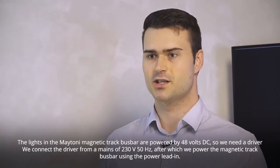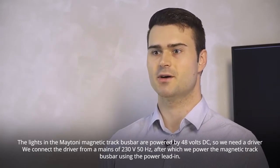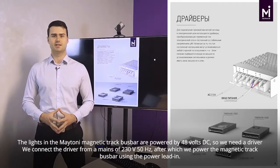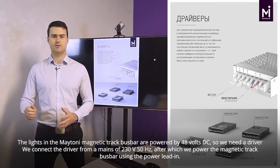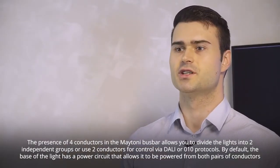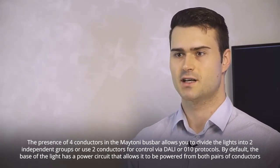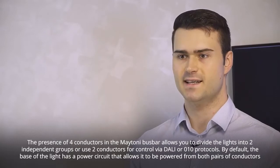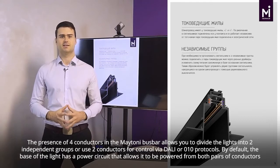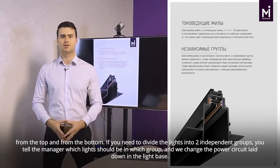The lights in the Maytoni magnetic track busbar are powered by 48 volts DC, so we need a driver. We connect the driver from a mains of 230 volts 50 Hz, after which we power the magnetic track busbar using the power lead-in. The presence of 4 conductors in the Maytoni busbar allows you to divide the lights into 2 independent groups or use 2 conductors for control via DALI or 0-10 protocols. By default, the base of the light has a power circuit that allows it to be powered from both pairs of conductors, from the top and from the bottom.